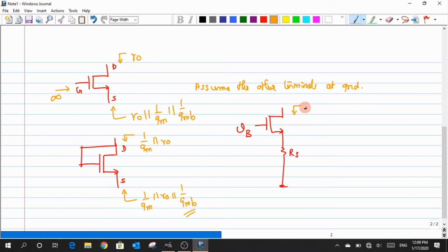For me, remembering the formulas is quite difficult, so I confine myself to using small tips to build the entire formula. That is how I remember all these formulas. Now that I know this resistance Rs has to be magnified by the intrinsic gain, the formula is approximated as Rs being magnified by the intrinsic gain of this transistor, which is Gm R naught.